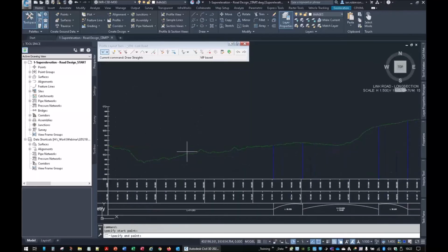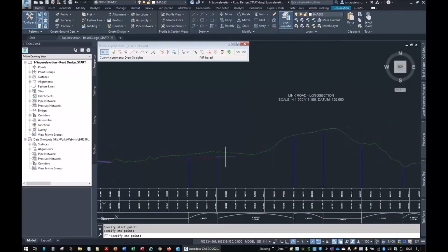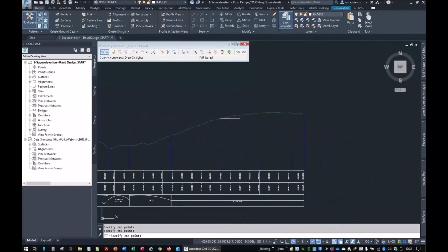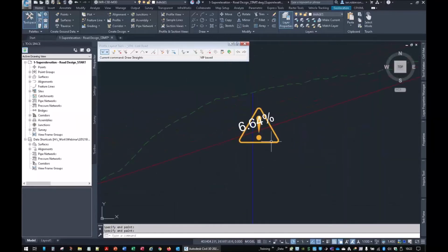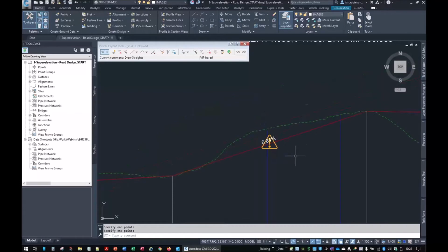And we will put something in kind of here. Maybe go over to here, up to here. We'll go straight across there and to the end. Now immediately we have a violation. Basically for the single carriageway, it's a desirable violation, but it hasn't violated our relaxed rule, so we could probably get away with that.